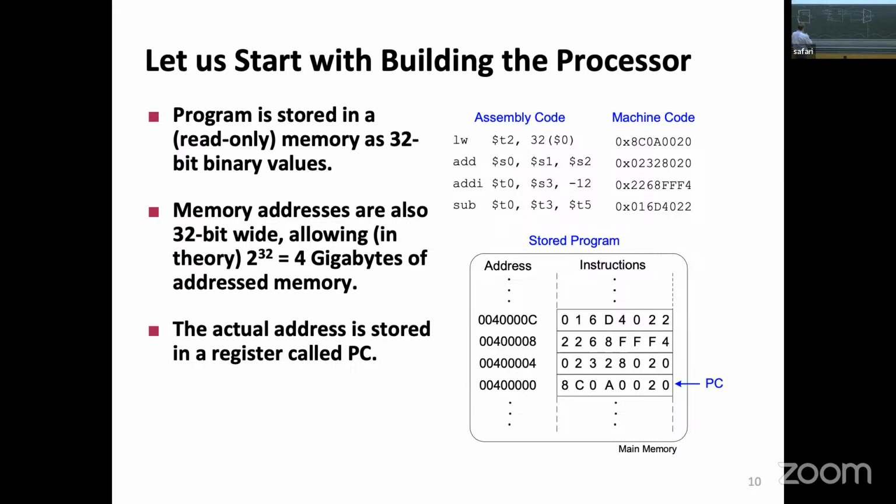So the same instruction also goes to this magical control cloud, which we will come to in a moment. So this is again the instruction. And in the control part, we will figure out which one of those ALU operations we should select. Now we have this output, and this output should go where? R-type instructions will write back to the register file. So we are taking this output, and we will bring it back, hopefully.